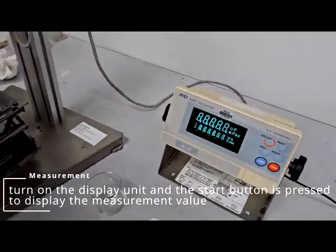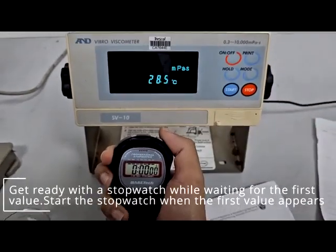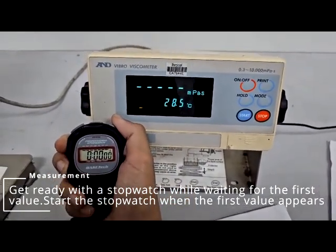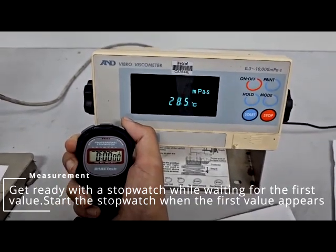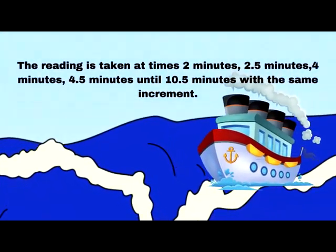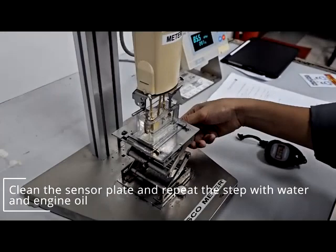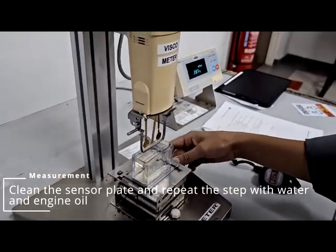Turn on the display unit and press the start button to display the measurement value. Get ready with a stopwatch while waiting for the first value. Start the stopwatch when the first value appears. The reading is taken at 2 minutes, 2.5 minutes, 4 minutes, 4.5 minutes until 10.5 minutes with the same increment. Clean the sensor plate and repeat the steps with water and engine oil.